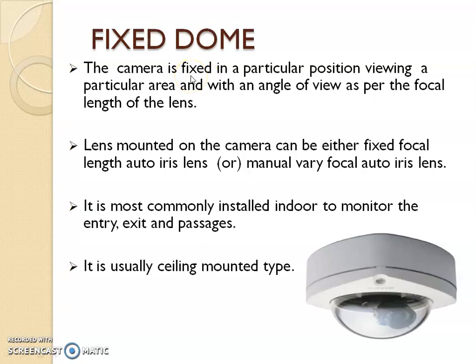The reason for a fixed dome is, if the camera is allowed to swing, there is a chance that there can be a security breach in that small time gap where the camera rotates and comes back to its original position. So typically these are installed in the entry and exit of a building facility.